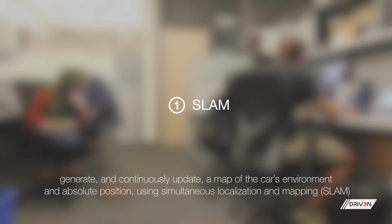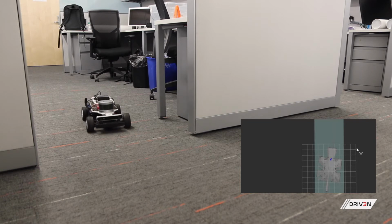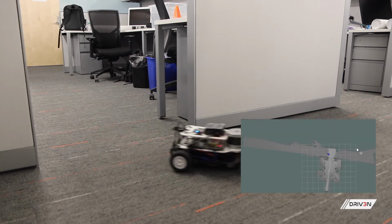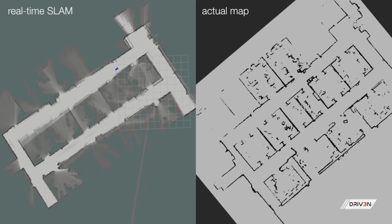The first objective of this challenge was to generate and continuously update a map of the race car's environment using SLAM. This allowed the race car to determine its position and orientation in an unknown environment. Due to the challenge of developing a reliable SLAM algorithm, we used an optimized ROS implementation of Google Cartographer for SLAM on the race car platform.